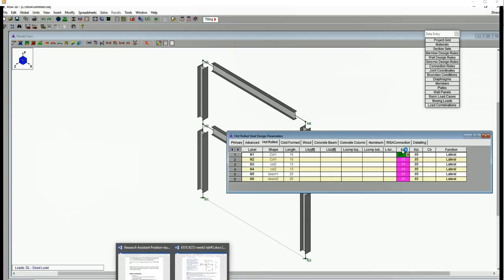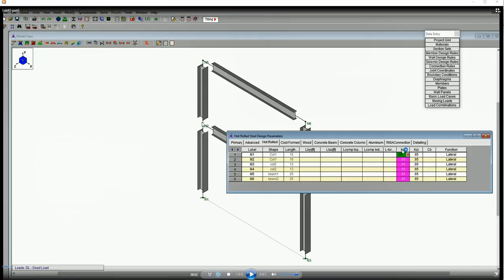So now we're going to do part 2, which will be applying the lateral loads on the same moment frame. This is the same problem, but we're just solving it for lateral loads. Moment frame means these columns' stability against the lateral loads is through the connections to the girders and horizontal beams that are connected to the other columns.